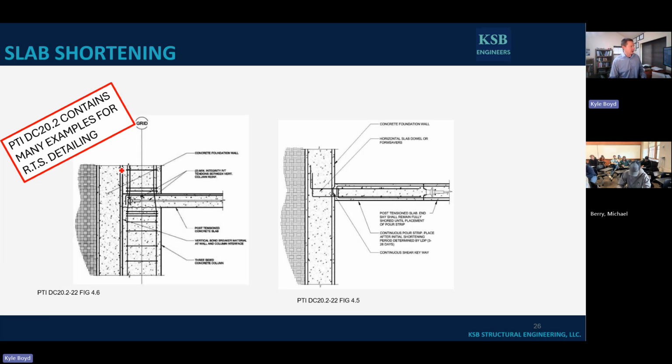This one on the left, that's what I was talking about with, hey, we have a foundation wall below ground. We still need that vertical support. Instead of trying to support that slab off that retaining wall below ground, pour a column, a 3-sided column up against that wall. Pour the wall first, pour a 3-sided column up against it, put a piece of masonite or slip material in here. Now this column, you know, it can pull away from the slab right there, right? So that's a really good way for us to try and support the slab vertically, but not hard tie it in that wall.